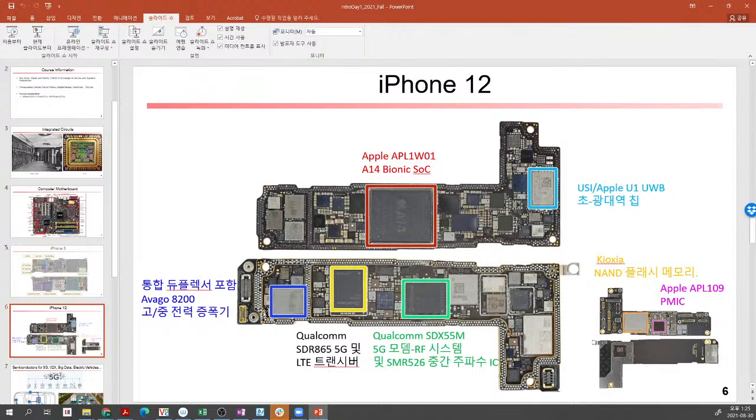We also have a duplexer on the left, which is an RF high-frequency component where transmit band and receive band filtering happens. And on the right-hand side we have the power management IC and memory elements like flash. As you can see, you have a very small computer system.